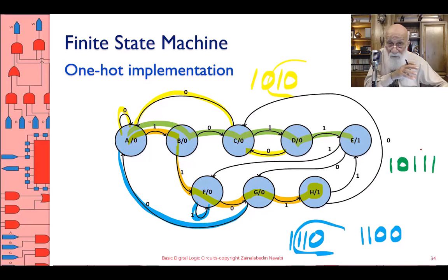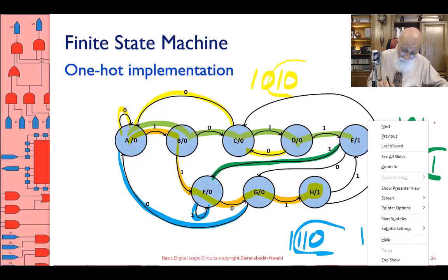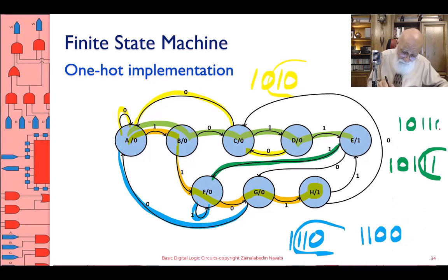You look for the most number of bits that you can salvage, or you can use towards either one of those sequences. Here, the most I can do is just 1, 1. So let's go to the state where a 1, 1 has been saved, and therefore a 1 takes me to this state. If you are in E and you receive 1, 0, 1, 1, you have already received, and then you receive a 0.